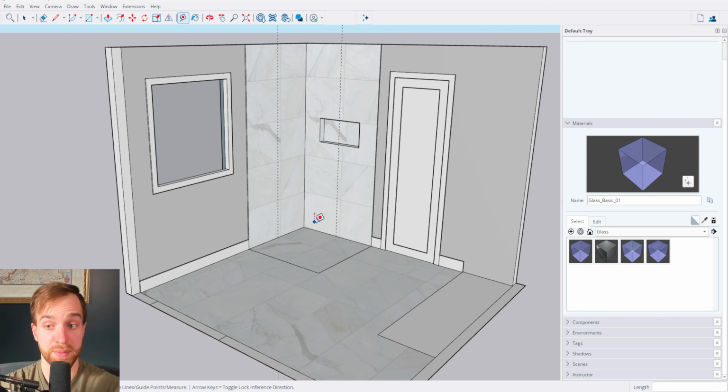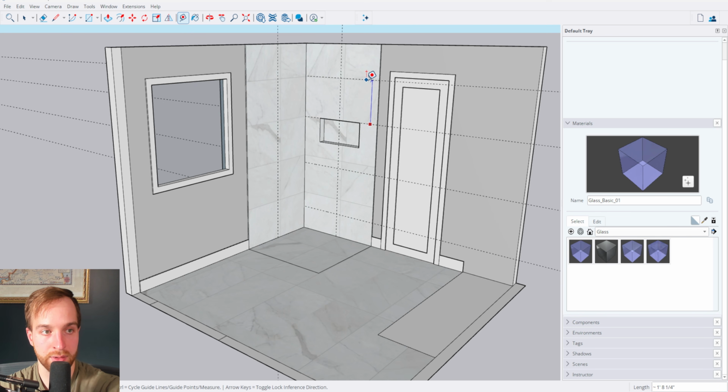Now we know from experience, or maybe some of you don't know, but even though it's an 8-foot ceiling, if we just took our 24-inch tile and just went up from a basic piece on the floor, because it's not actually 24 inches, we'll end up with a little sliver here. So something I might do instead is start with, say, a 1-foot piece, right? And then from there, after that, we'll have 24-inch pieces. And the way that I design this should be that the niche kind of lines up with that grout line. And then we'll go up and we'll finish off in the drawing.